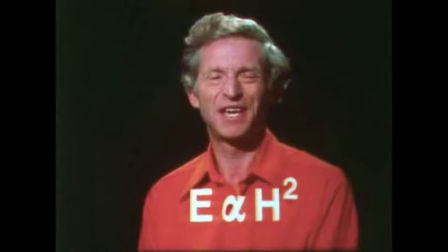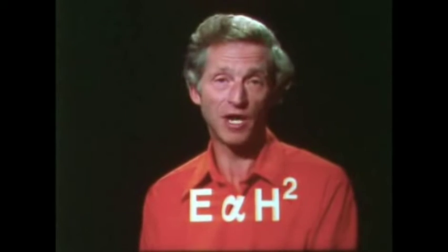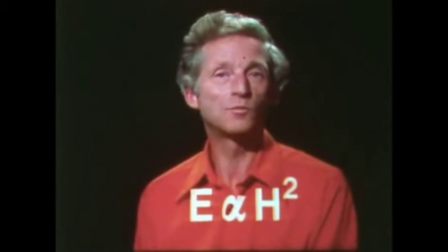Well, where does wave energy come into all this? From your own experience, you'll know that large waves carry more energy than small ones. And I expect you'll remember from the unit that the relationship between wave height and energy is not a simple linear one. Energy is proportional to the square of the height. So by measuring the height of a wave, we can find out its energy.